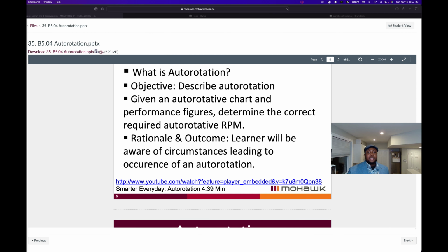We're using that flow of airflow up through to generate lift from the main rotor system without the use of an engine. In other words, the way that gyrocopters operate. So during normal flight, this is the direction of airflow. During autorotation, it's the opposite. Because the helicopter's direction of flight is downwards, air is now flowing up through and producing lift. The lift is produced by something known as the autorotative force. This force keeps the rotor turning as the helicopter descends during autorotation.